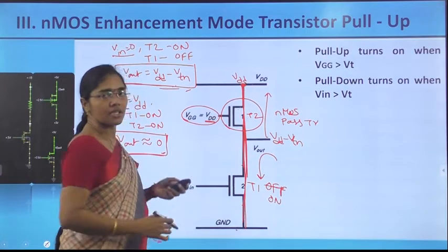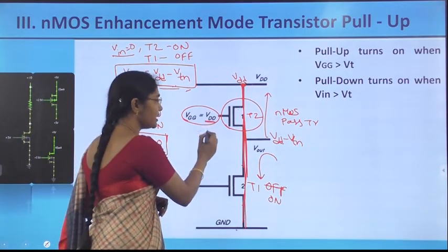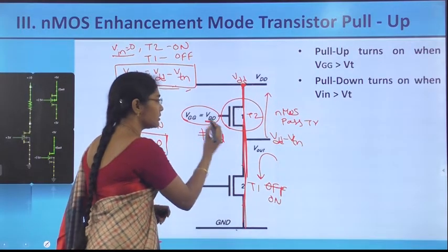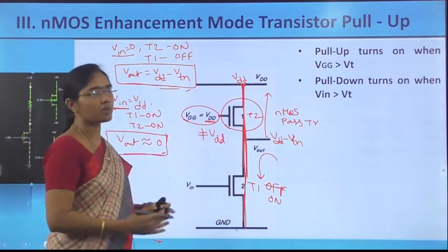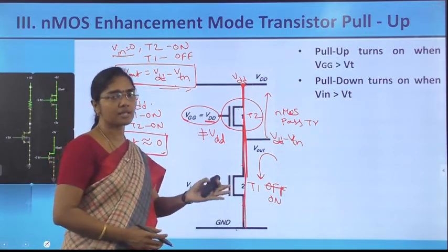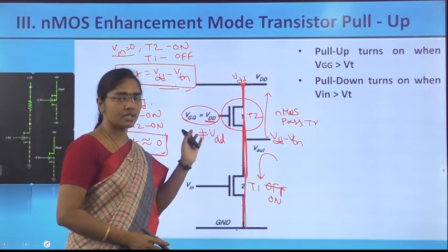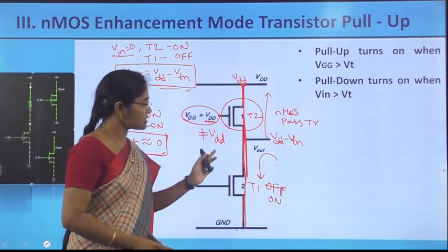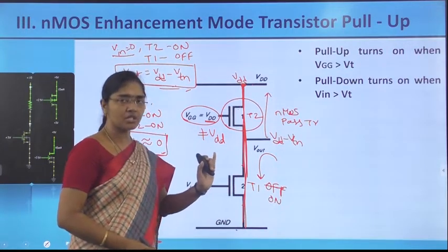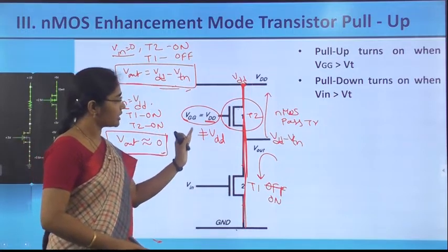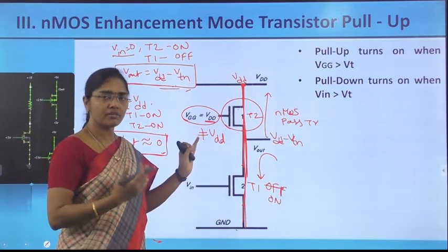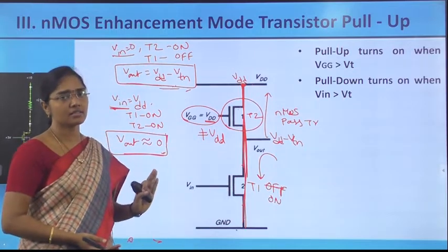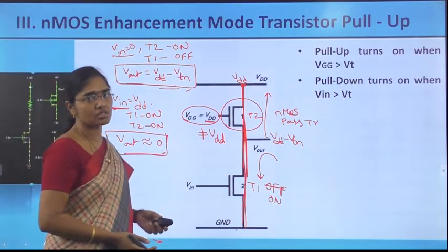If it is not equal to VDD, then we need to use one more extra power supply here. So two power supplies are required if the gate supply is not VDD. That means outputs are not full swing, a gate power supply is required if it is not equal to VDD, and static power still exists in the circuit. These are the problems with this circuit.